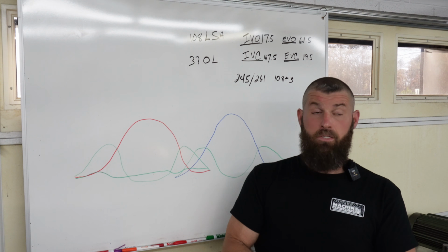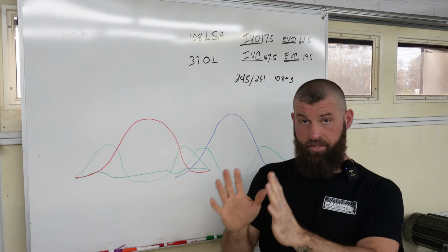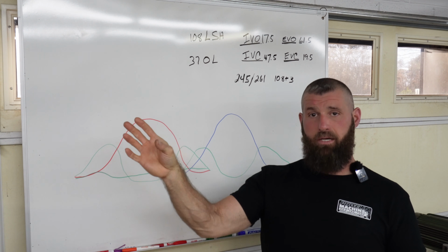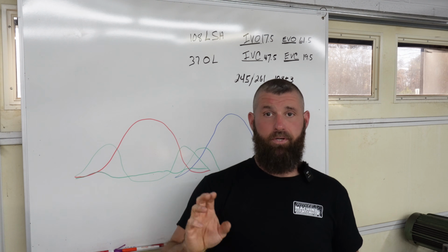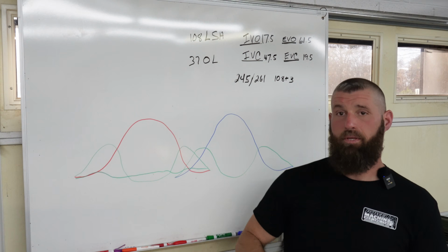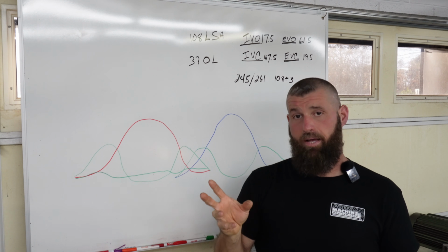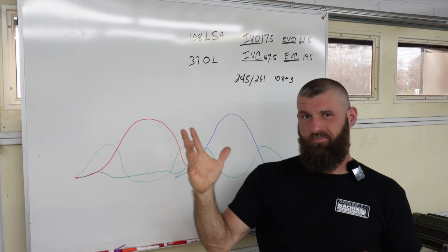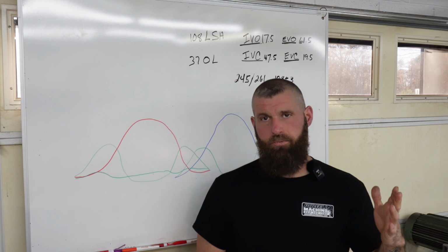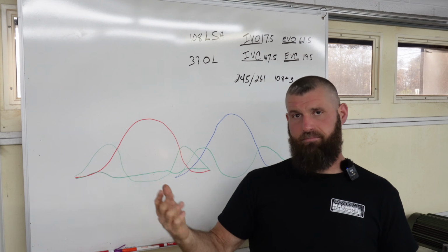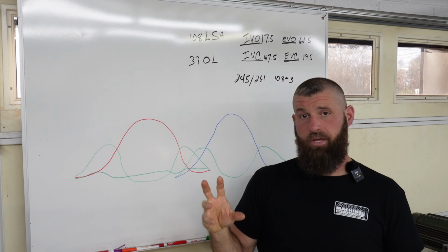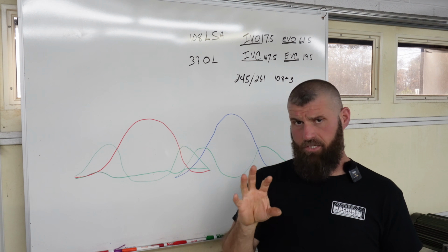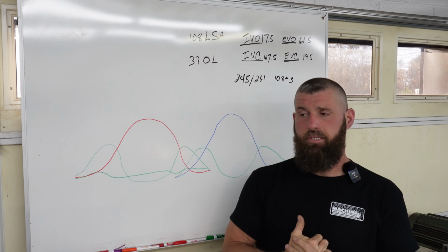He said, absolutely. So what we're going to do is that, plus he said, hey, I would love for it to peak a little further up. So can we do another cam and see if we can get the RPM up? Absolutely. So I have spec'd another cam to try to move the RPM up. You know, I think it peaked at like 62-ish, and he wants to peak around 65, 66. So I done another cam. I feel confident that it's gonna go another 400 or 500 RPM, and that's where he wants to be.